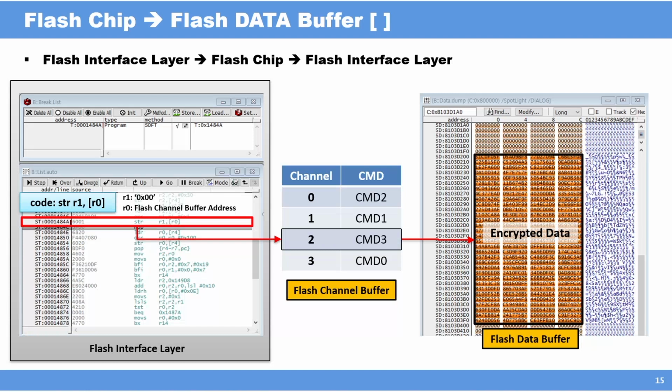If the target has hardware-based whole disk encryption to encrypt every piece of data, we need to cross-check to make sure the data is actually read from the flash chip. So we pick any plaintext data and write it to the SSD, and we already know the right buffer address where the ciphertext comes in, so we can check whether this ciphertext and our readout data from the NAND flash chip are the same or not. Finally, we can be sure that this is the flash data buffer address.